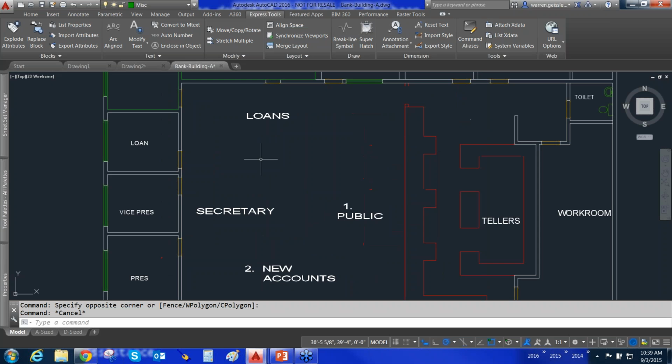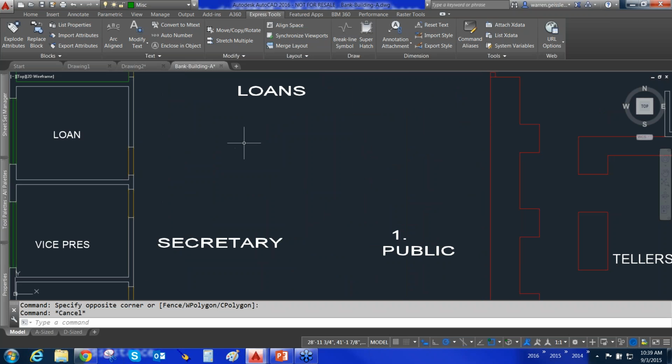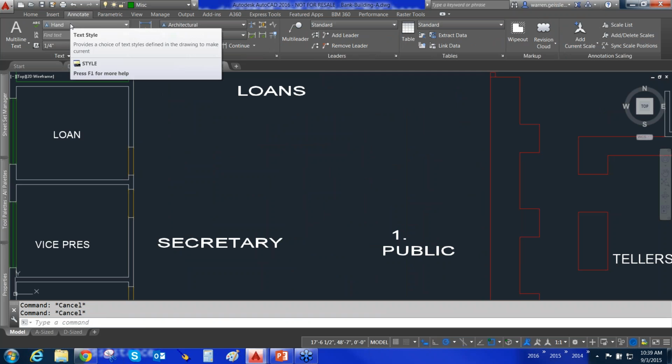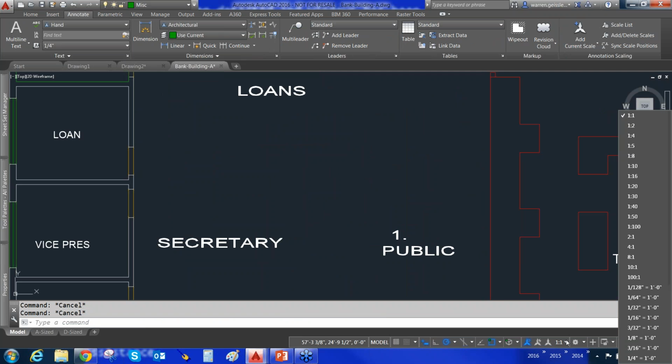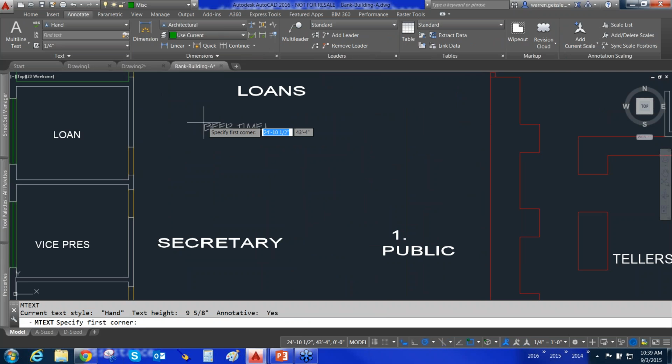You know what, speaking of text, you know when you start the text command and it has the letters A, B, C? Let me change my text style and change my text height. I want to put in some text, and whoops, let me get that out of the way. Mine doesn't say ABC, does it? No, it doesn't. How do you change that piece of text? It's a neat little thing. It's great to show off maybe a company name. We used to do this during demos and all of that.